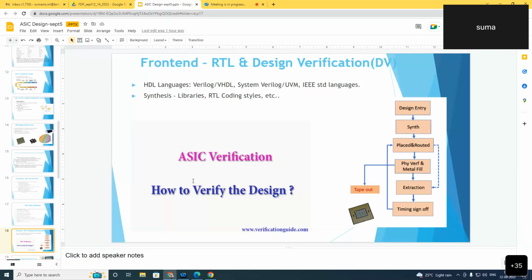And as we know, library developers may define any number of operating conditions in the library, and the library is characterized using one set of operating conditions. But when we talk of PVT, the process, voltage, and temperature, we should see that the process will always vary from 0 to 1, the voltage variation will depend on the technology being used, and the temperature varies normally between 0 to 125 degrees centigrade.